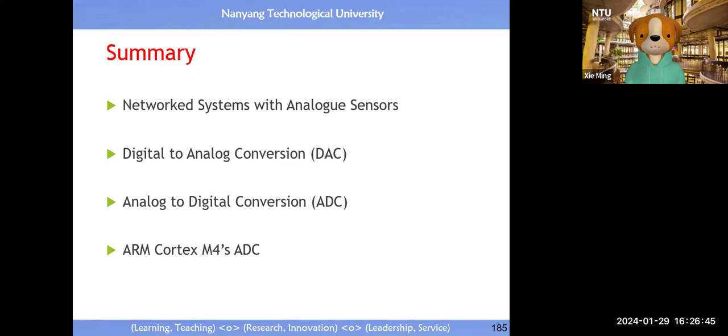Conceptually, it's very simple, and this device is very powerful. Because we have a 12-sensor input, internally we offer you a sampling device plus a quantization device, and also a pair of comparators to do hardware-based monitoring of whether the sensor output is within the upper and lower limits or beyond them.